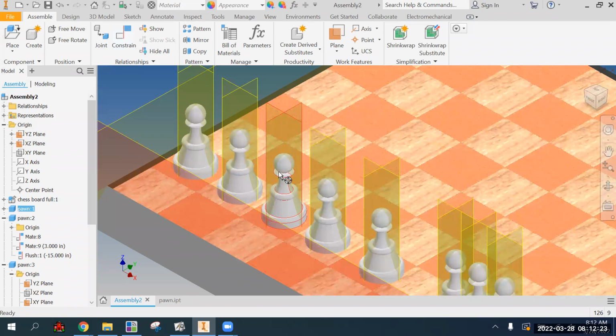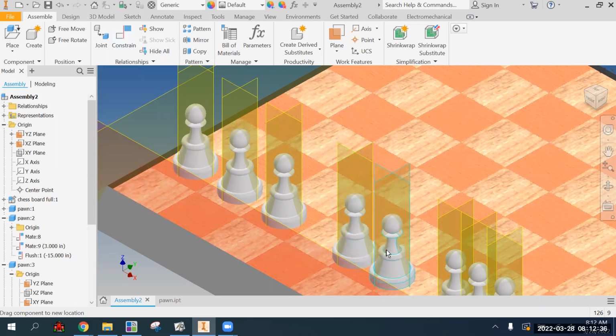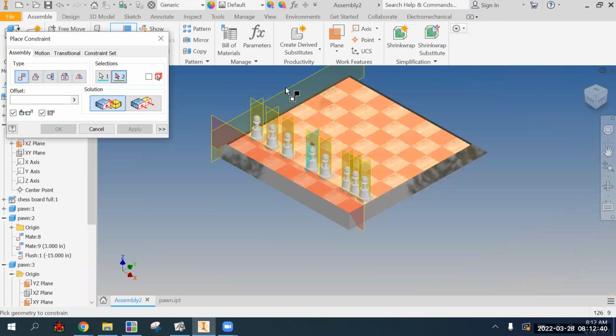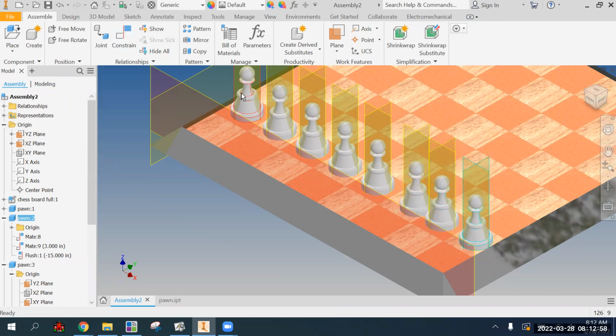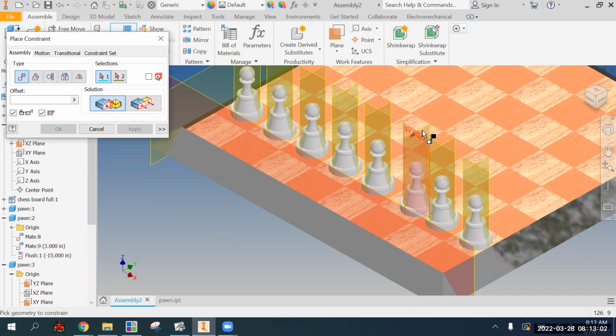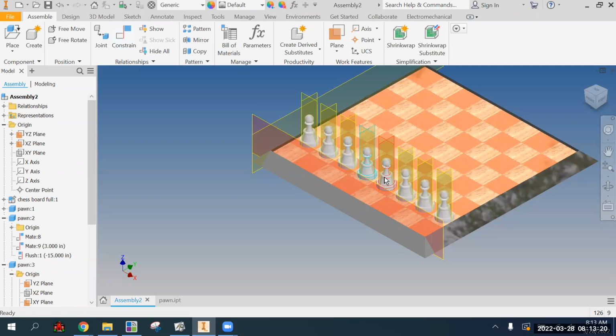And you shouldn't be able to click and drag anything if it's fully constrained. So we need to do, I've actually made this unnecessarily complicated for me. So we need to do this one. This needs to be -7. -9. And I think I only have one more. No, 2 more, and that one's constrained. So do this one, is -11. This one, -13. Okay. So you should be able to try to drag them and not be able to drag them. Okay, and I would say save relatively frequently.